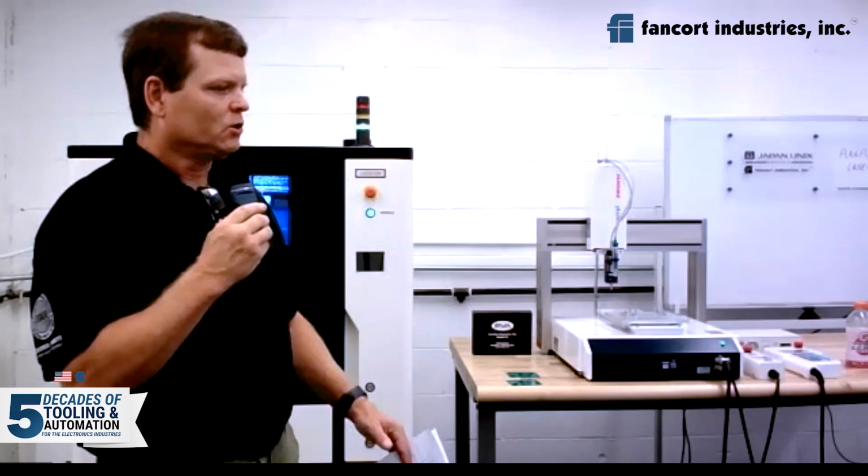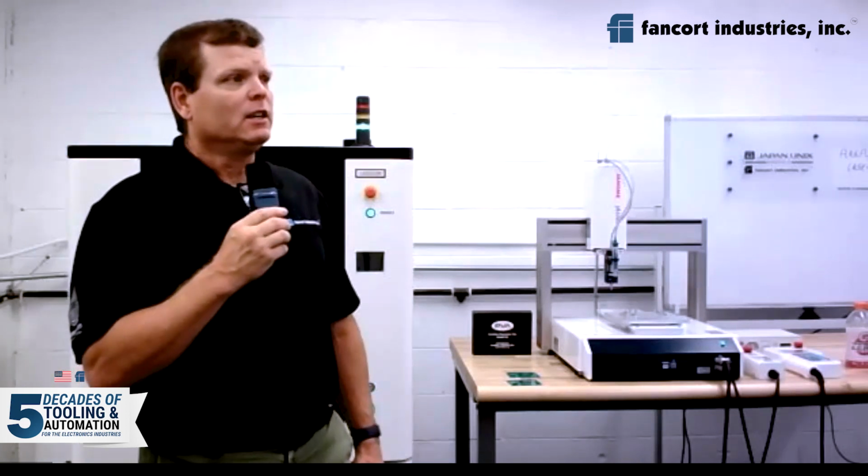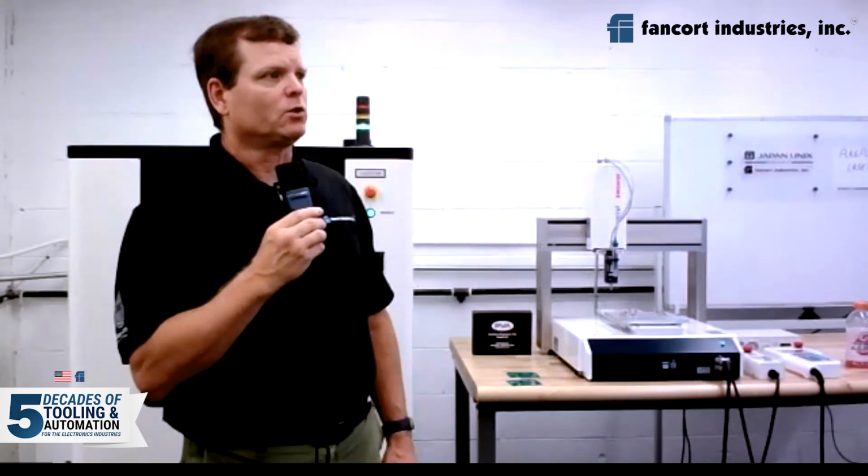Another question here. How many cycles is your laser guaranteed for? Oh, boy. It doesn't really go by cycles. We rate the laser we use for 2,000 hours. That doesn't sound like a lot, but the laser is only on for a split second to either solder multiple joints, as we're showing in the area laser soldering, or solder one solder point, so it takes a long time to add up to that. And in reality, the laser will go beyond that 2,000 hours, that's for sure.